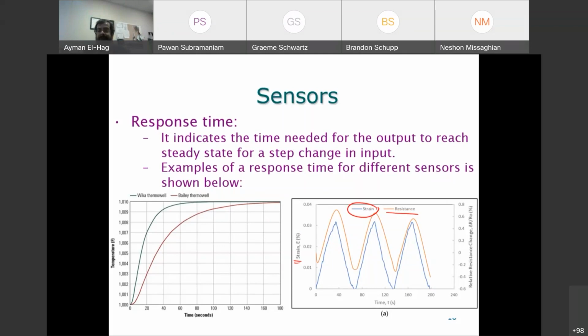Then you have to give it some time until you see the temperature varying, especially if you bring a source of heat to the sensor, you will see that the values are changing, and then it will start to settle down. So understanding this, that the sensor needs a response time. You don't just take the value right away.